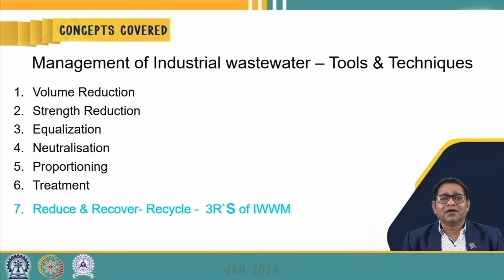What are the various tools and techniques? What are the impacts of equalization? How can we equalize the wastewater, its characteristics, its pollution load? Then there is neutralization, one of the important tools and techniques adopted. Some waste streams are acidic in nature, some are alkaline in nature. By mixing these two different types of waste streams, one alkaline and the other acidic, we can neutralize the pH of the wastewater, which is mostly required for its further treatment and disposal.